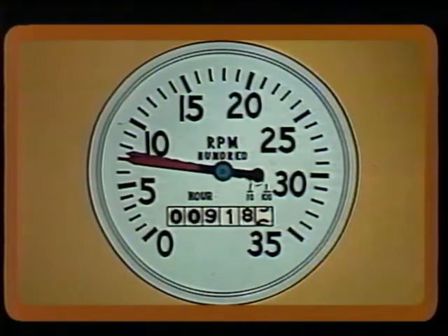Adjust the idling RPM by setting the throttle stop, and check the idling mixture by slowly pulling the mixture control into the idle cutoff position. There should be a slight rise in RPM before the engine stops entirely. After the system is checked for the proper unmetered fuel pressure and for the proper idling RPM and mixture, it must be test flown to check metered fuel pressure against the specifications established by the manufacturer.